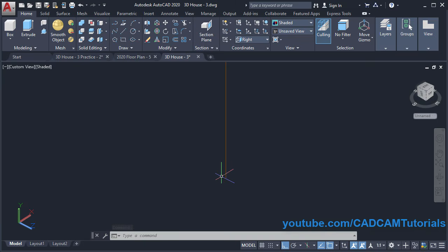At first we will have to create cross section of frame, so that cross section will be horizontal. Therefore we will need top plane. So click here and click on top. So here now XY plane is horizontal. Then click on polyline. Then click here, take your cursor on this side.